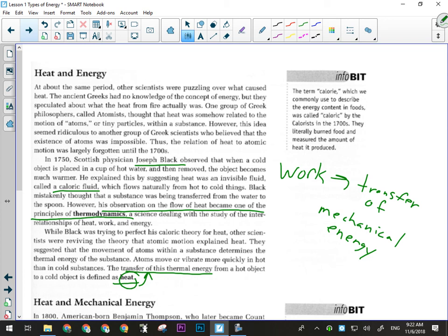And we have a problem with that in our society because we put something in the fridge and we think we transfer coldness. But in fact we don't. When you put something in the fridge, the heat from it goes into the coolant. If you ever pulled out a fridge, it's got that kind of grid on the back, and there's a big compressor on the bottom. That's the thing you can hear running when the fridge is running. The heat from the stuff you put in the fridge turns the coolant from a liquid to a gas. It absorbs the energy, so the heat is transferred from your food to the coolant, not the cold from the coolant to your food. You can't transfer coldness. You can only transfer heat.